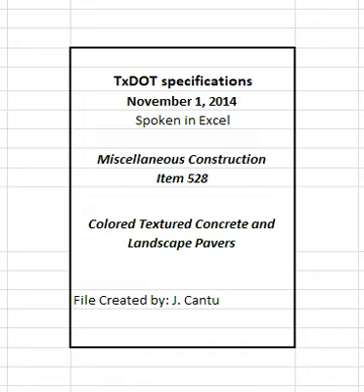5.3 Landscape pavers, furnished. The work performed and measured as provided under measurement will be paid for at the unit price bid for landscape pavers, furnished, TxDOT. This price is full compensation for loading and transporting, placing, and compacting pavers, bedding and joint filling sand, and equipment, labor, materials, tools, and incidentals. Paver units damaged during loading, transport, or compaction will be replaced at the contractor's expense. Base required for landscape pavers will not be paid for directly but will be subsidiary to this item.